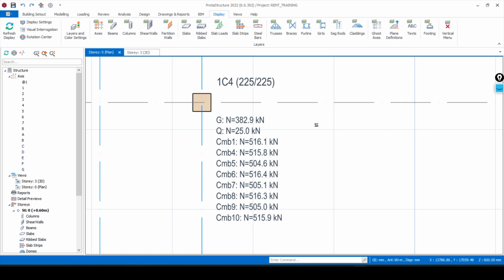So it depends on the use of your building or on the weight of the structure, depending on the kind of imposed load mounted on it and how wide apart your columns are spread. It is going to give you higher axial loading values, even up to 3,000 kilonewtons and all that. So it is going to affect the type of foundation that you are going to choose. I hope that is clear.